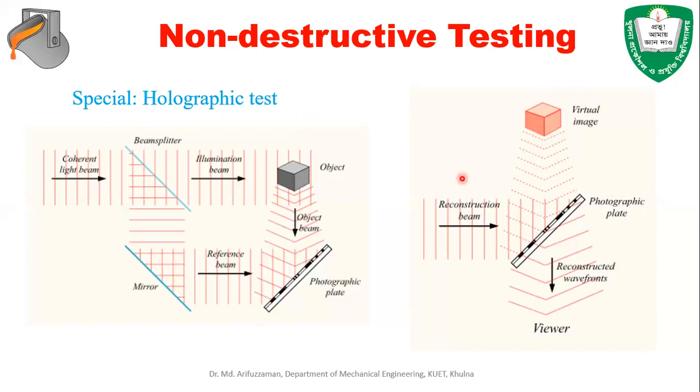But the purpose of this holographic test is not to create the virtual image. Instead, you will be examining the photographic plate. If you examine the photographic plate, you will be able to see the interference pattern, and that will show whether there is a crack or not.